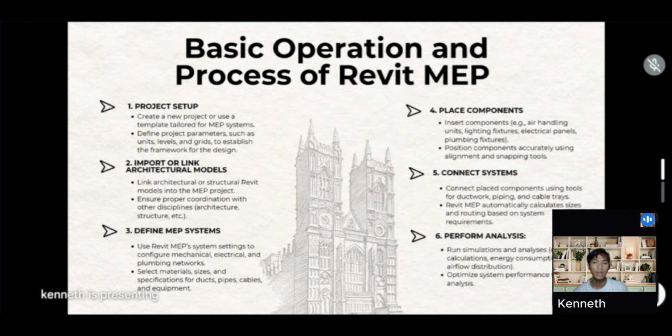The sixth is perform analysis. The final step is to analyze the performance of the designed system. Revit MEP includes powerful simulation tools to run various analyses such as load calculation, energy consumption, and airflow distribution. These insights help designers optimize the system before the construction begins. This ensures that the MEP systems are not only functional but also energy efficient and compliant with the industry standards.